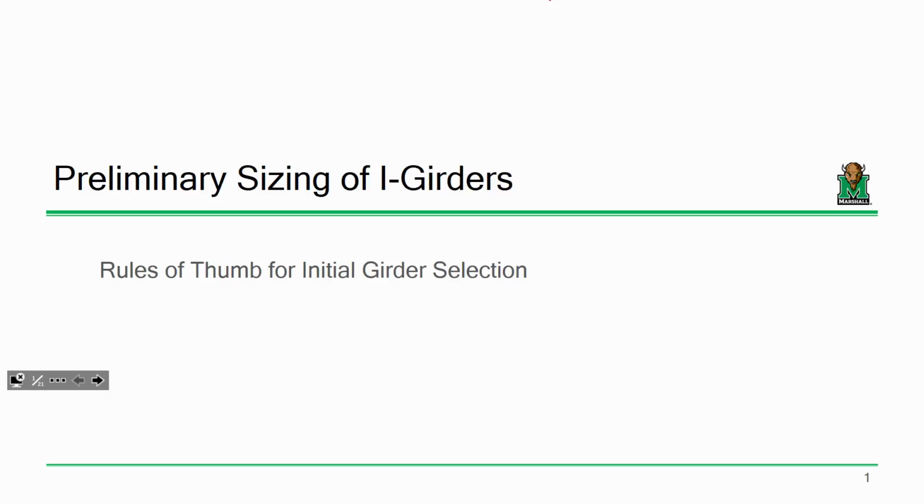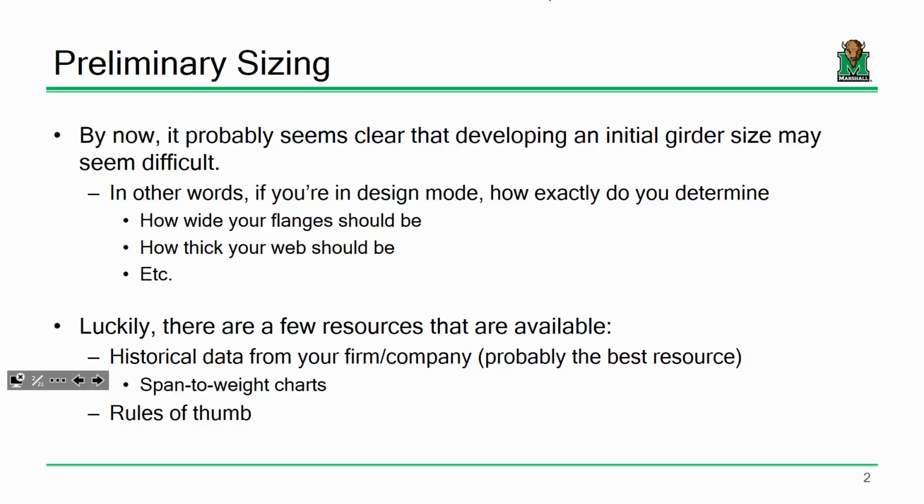Okay? But what you're going to find is maybe that girder is not good enough. You calculate all your capacity and you find you've got phi Mn, you've got Mu, there's too much Mu so the girder fails, so you've got to change your dimensions. But you've got to start somewhere, okay? So that's what I'm going to talk to you about, okay?